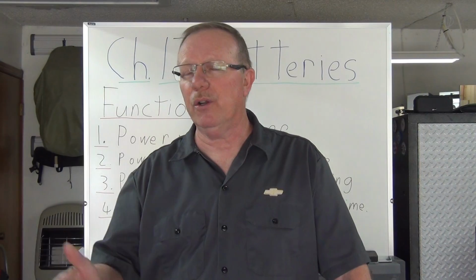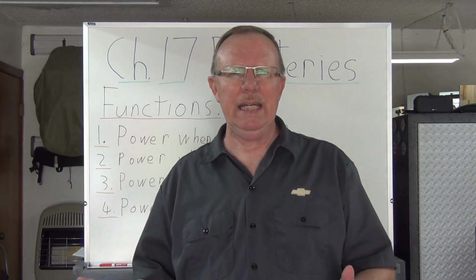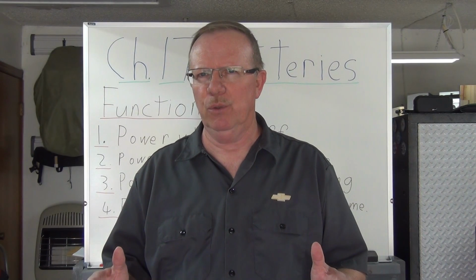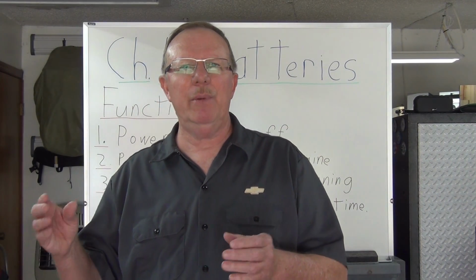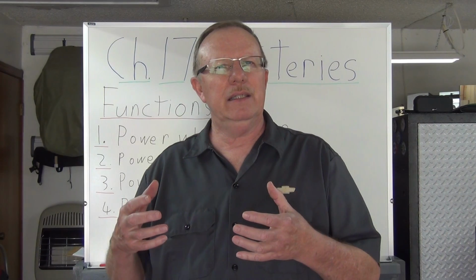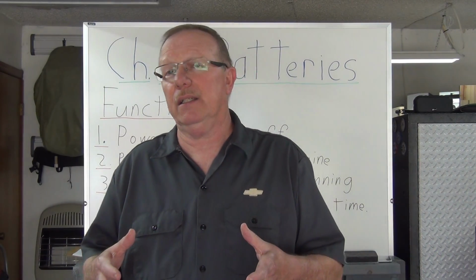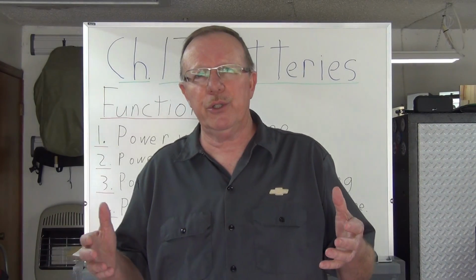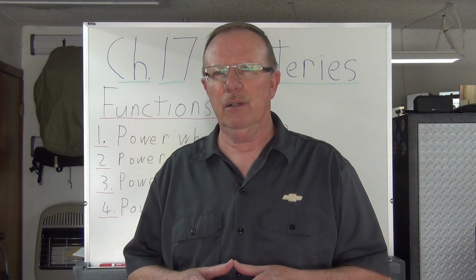So that means that when there are power surges, when the alternator's charging, or when the starter's cranking and that voltage fluctuates or that current draw is more or less, the battery acts as a cushion, if you will, as a voltage cushion. It cushions that. It keeps that from happening just instantaneously. So when there's a high load like 150 amps cranking, it absorbs some of that load in a sense and keeps that from happening all the way. It does that to protect itself, one thing, but it also does that just so that there's a smooth operation all the time and delivery of voltage and current to the car. I hope that makes sense.